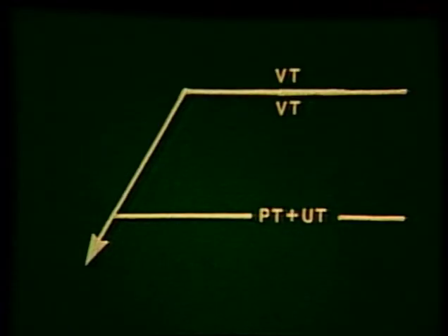For example, these multiple reference lines call for liquid penetrant and ultrasonic inspection to be applied with no particular side significance. The second operation specifies visual inspection to be performed on both sides.